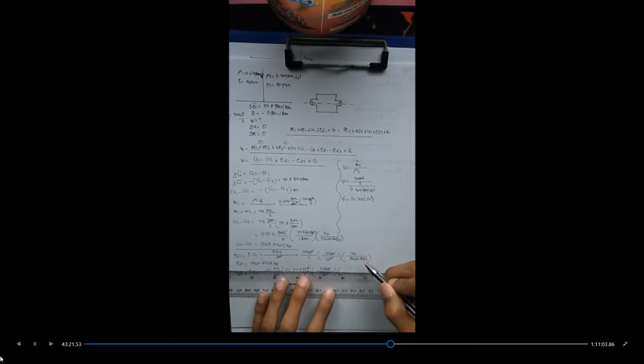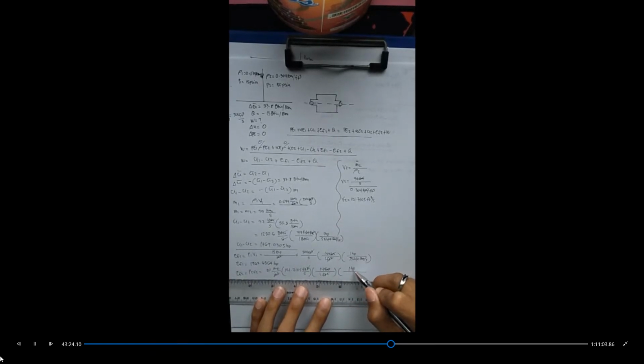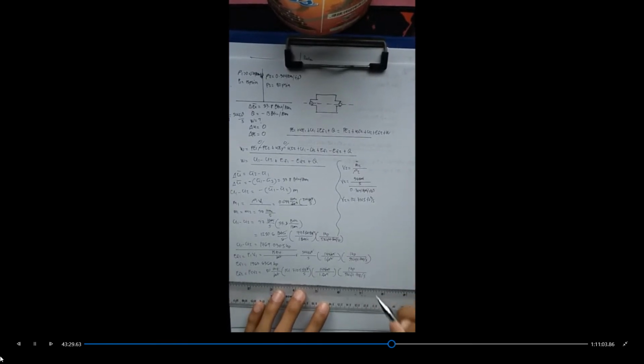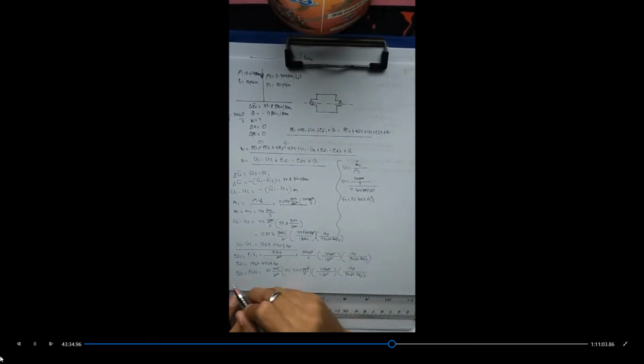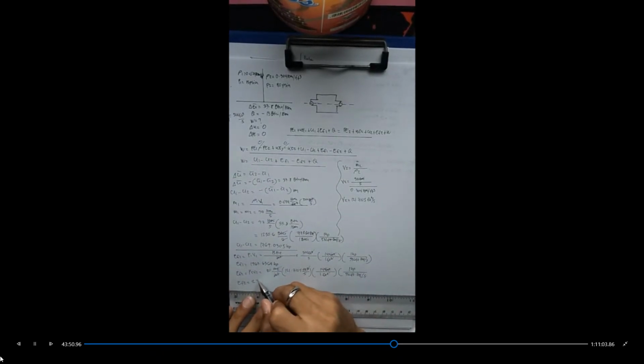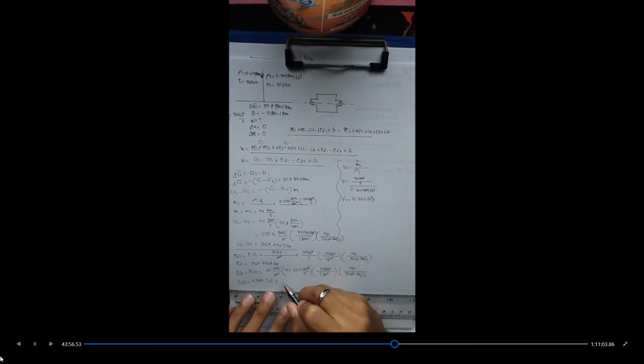Converting to horsepower, 1 horsepower is 550 foot-pound force per second. So flow work 2 is 80 times 121.7105 times 144 divided by 550, and the resulting value is 2549.2817 horsepower. That's for our flow work 2.